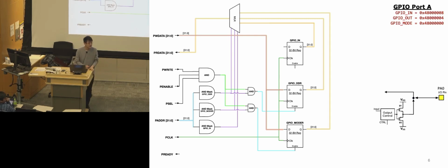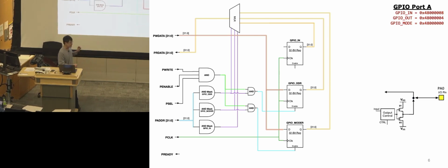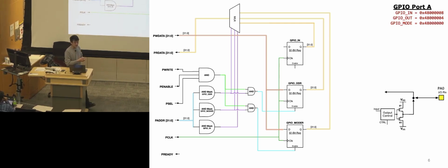When would the P enable be true and the P write be false, or vice versa? Under, say, a read instruction, so like a load. They're not really storing or writing anything. It's just loading or reading from a certain register. Then the P write will be low, and the P enable bit is set by the master or by the requester.